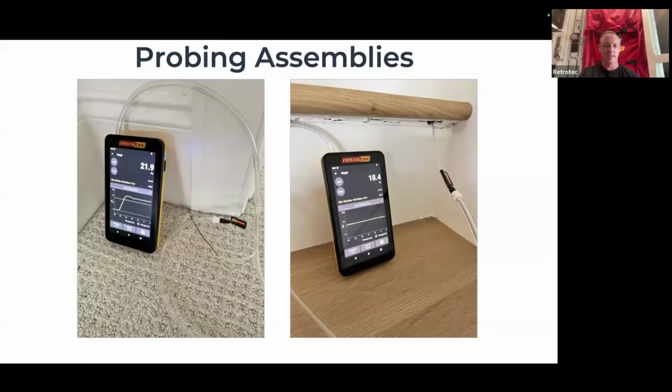So now I'm reading some activity inside that wall cavity, and I'm getting quite a bit there. I'm reading about positive 22, and the blower door is running to negative 50. If I'm reading that high of a pressure, that means I've got quite a bit of air leaking into that wall cavity from somewhere. That's a high number to read. I usually want to see that number a lot lower if I'm going to determine if it's airtight or airtight enough. But if it's keying into the 20s, that's significant.